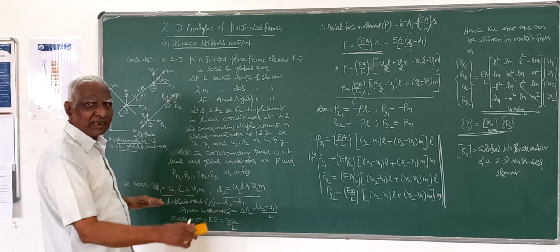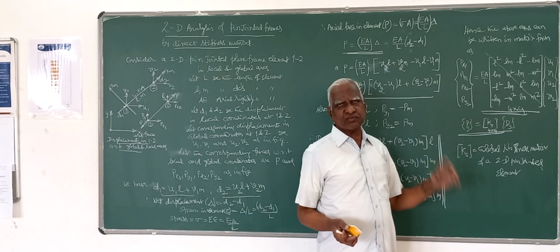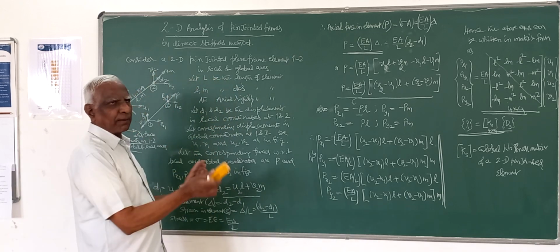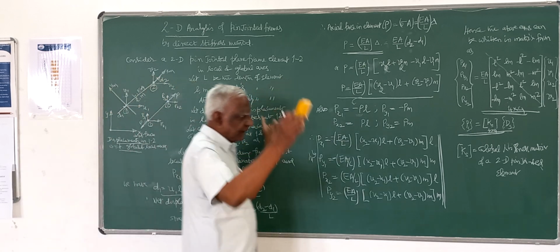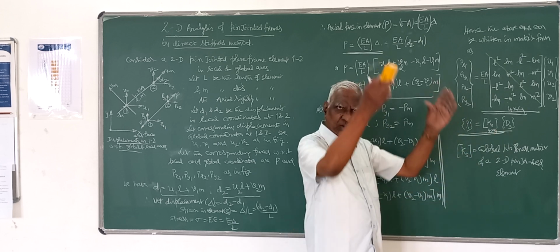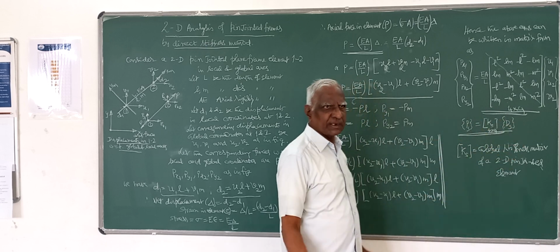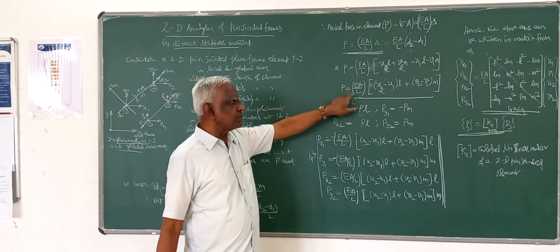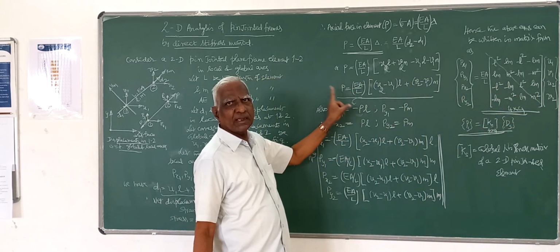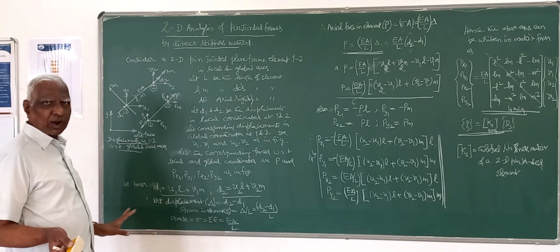After doing all that preliminary data collection, you can compute the stiffness matrix by remembering this formula straight away for all the elements, then compute for the entire structure by combining all the elements. Then for the entire structure, you can write this force displacement relationship. Loads are also known at all the nodal points. Given these, you can easily determine the displacements. After determining these global displacements, you can compute the element member forces. That's the general procedure, and we will work problems on that.